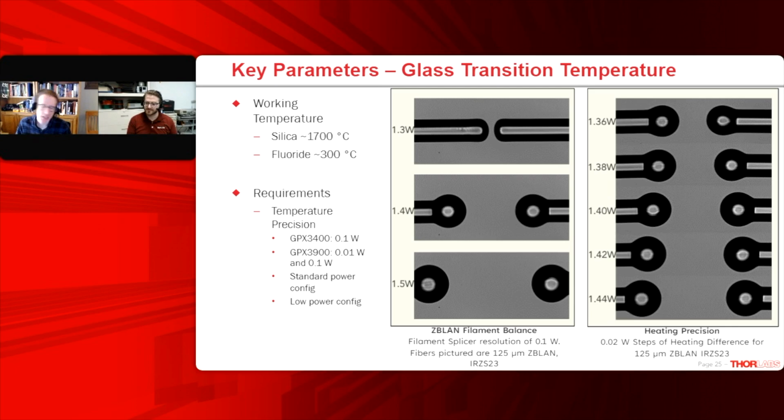And so when you couple that with, yeah, it's hard to make the fiber consistent. Obviously, at Thorlabs a big focus for our fluoride fiber is manufacturing consistency, but we live in the real world, and it's hard. And this glass is very sensitive to temperature changes. In my opinion, that kind of swamps everything else, like filament geometry and things like that, when you see these differences from day to day. As Tyler said, there's no standard fiber.